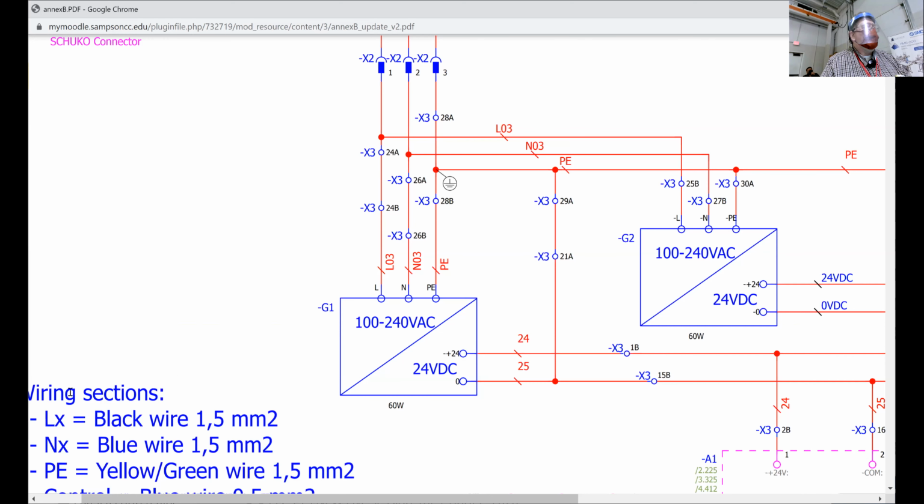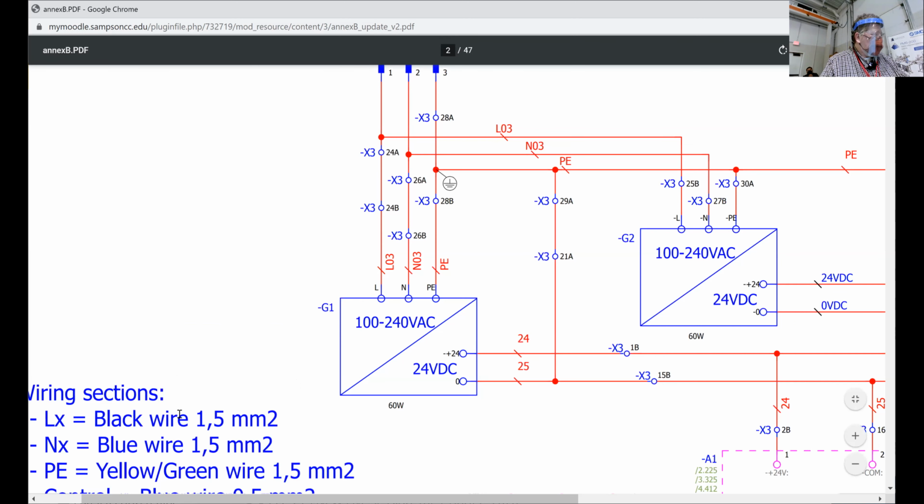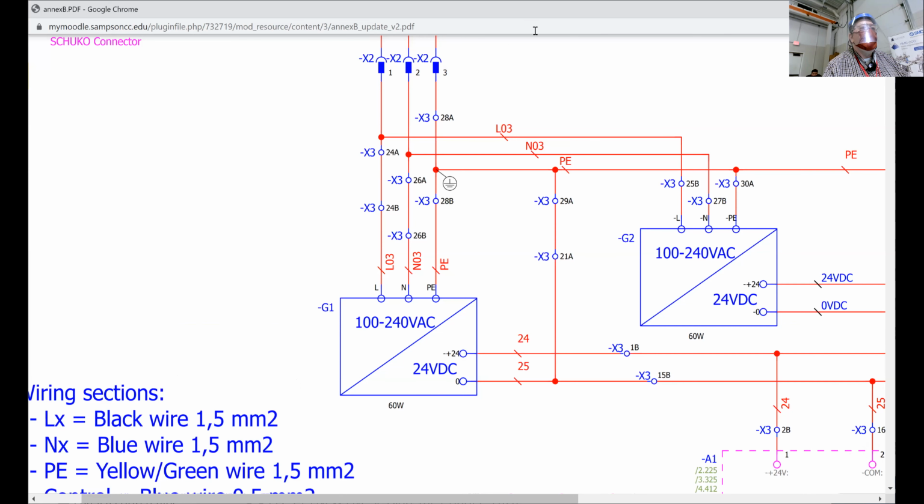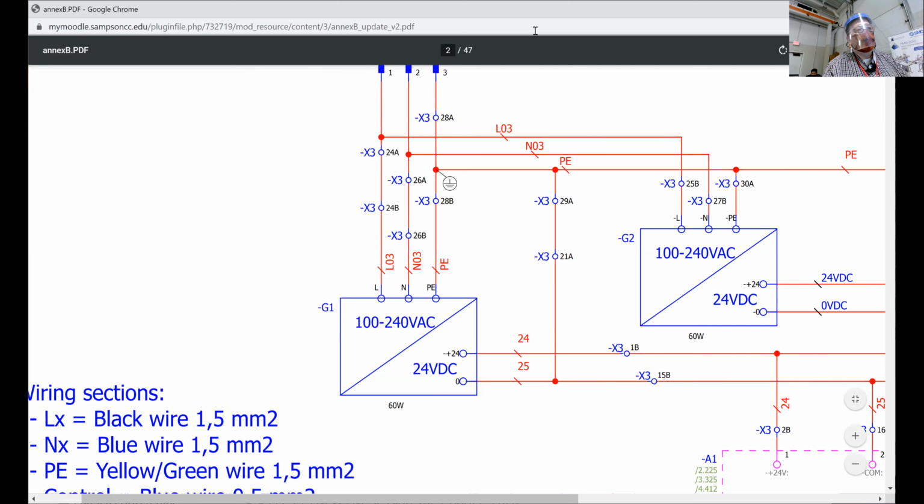Let me flip over to the lab paper itself. Now hold on. The power supplies, when you get to those on your lab sheet, are going to be power and control, P/C, because they accept main power and then they produce control power. But everything downstream from these is going to be control power.